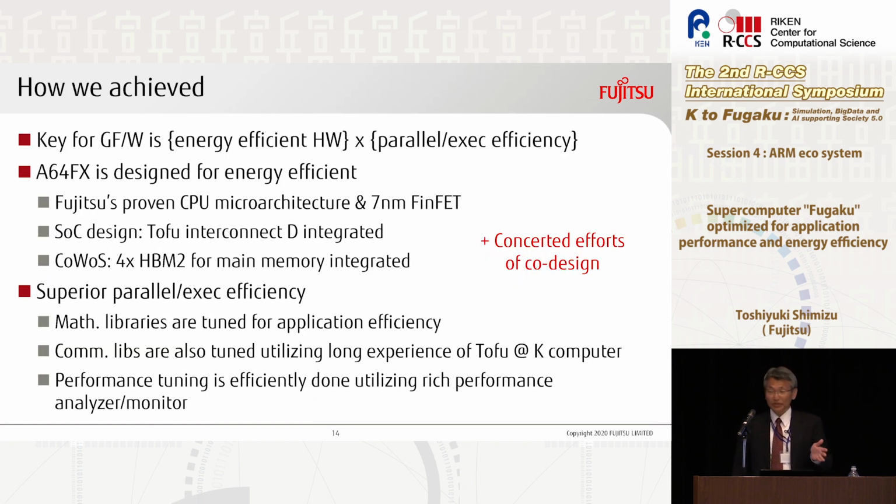The point is a combination of hardware and software optimization. Hardware side, A64FX is designed for energy efficiency. Fujitsu proven CPU microarchitecture and leading-edge silicon technologies. And TOP500 interconnect is integrated into the CPU chip, and memory is also integrated into the packages using CoWoS technologies. So only the CPU packages are required to build the Fugaku system.